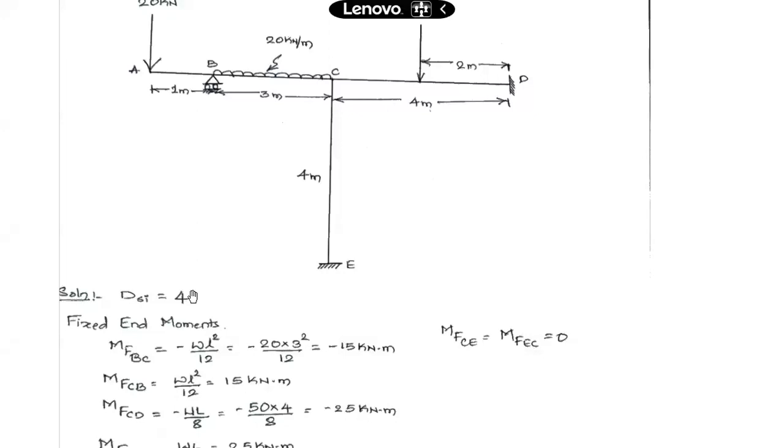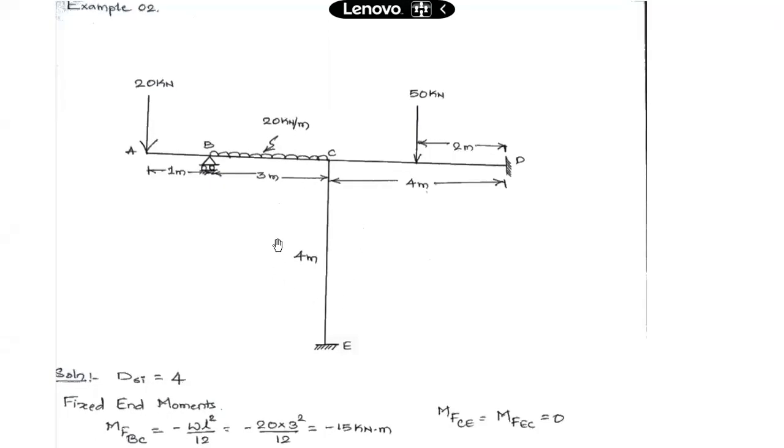In the slope deflection method, it is mainly a displacement based method because we are treating displacements as our unknowns. In our equation, we come across theta and delta. They are displacements. So what we will be looking for is the degree of kinematic indeterminacy. Rotations at B and C are the unknowns, so the degree of kinematic indeterminacy will be 2. Eventually we'll get equations in terms of two unknowns in the slope deflection method, which we will solve by taking help of the conditions of equilibrium.